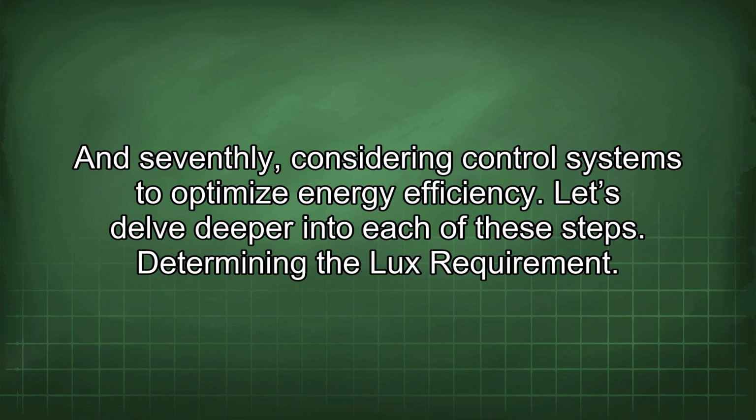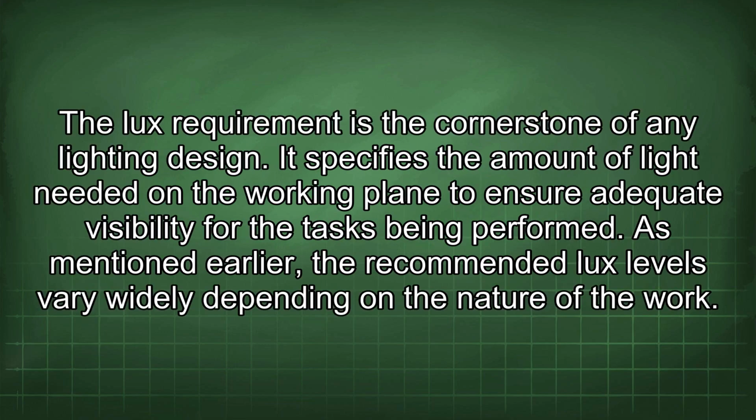Determining the lux requirement. The lux requirement is the cornerstone of any lighting design. It specifies the amount of light needed on the working plane to ensure adequate visibility for the tasks being performed. As mentioned earlier, the recommended lux levels vary widely depending on the nature of the work.